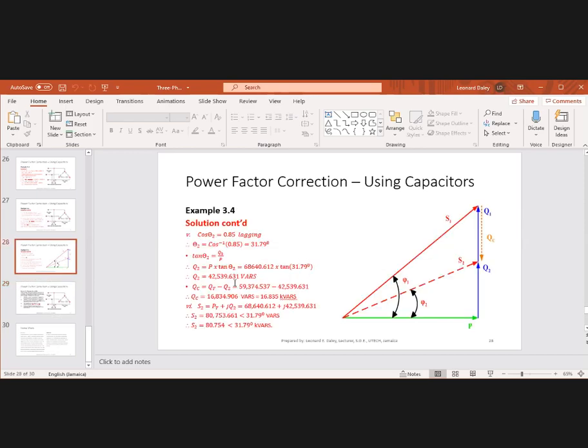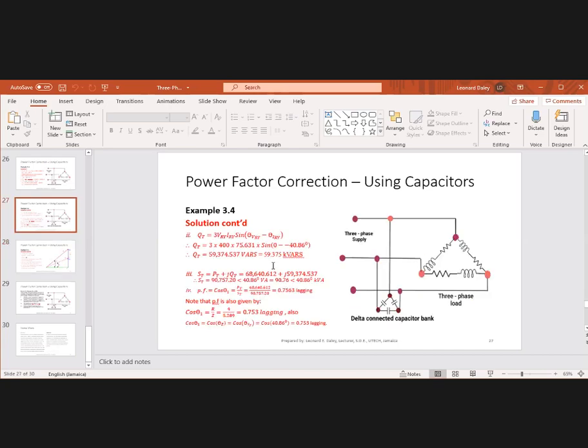So you can go back to the apparent power. S is equal to root 3 VLIL. Or since you had found the phase current before, you just multiply that by root 3. When I did the apparent power method that you just told us, I got 131 and it was close to the 130.99. Okay.